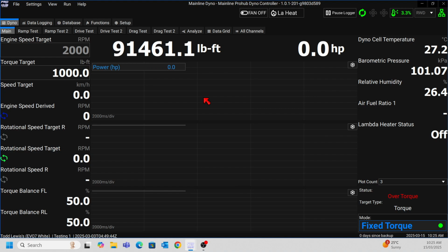So you can drive along with various load. You could go through the gears, you could run an engine in if you wanted to do this particular function. So it's one major big change on the CCS system compared to the Dyno system, having this torque value target you can actually control. But just be careful using this function here. If you're pushing page up and putting more and more load on, if the vehicle can't sustain it, it'll basically just stop the vehicle. So you have to be aware that you're going to have to press page down back to 0 pretty quick smart if you want to drop the load off when you're doing that particular test.